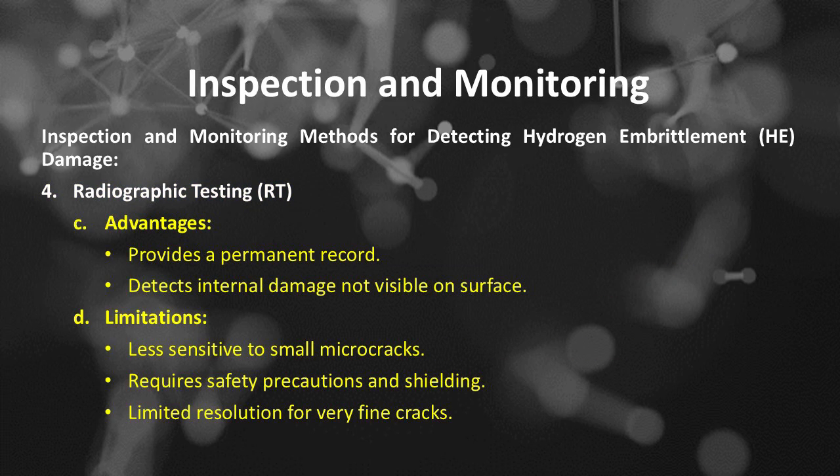Radiographic testing advantages include providing a permanent record, and detecting internal damage not visible on the surface. Radiographic testing limitations include being less sensitive to small microcracks, requiring safety precautions and shielding, and limited resolution for very fine cracks.